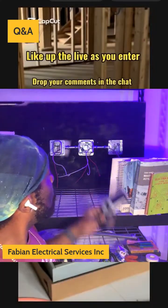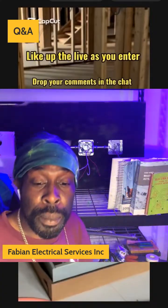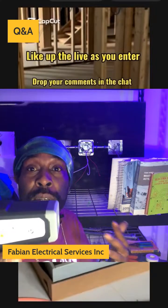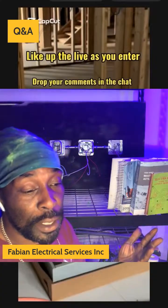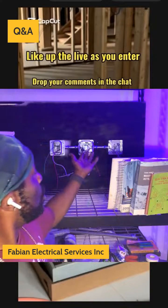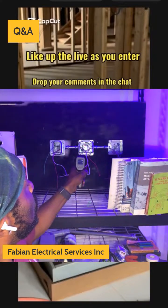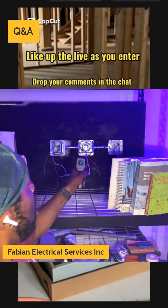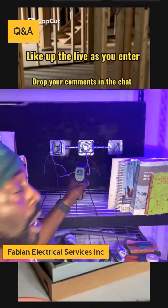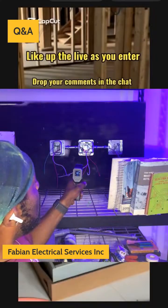And again, in order to trace if there's heat in there, you're going to want to use a digital infrared thermometer. It's a Husky brand. Simply, this will detect the temperature if there's going to be an overheat and so on inside of the box. You simply turn your light on, point it into the box, and it's going to give you your reading here. Okay, it's going to fluctuate up or down. It's going to let you know if there's some kind of overheating.